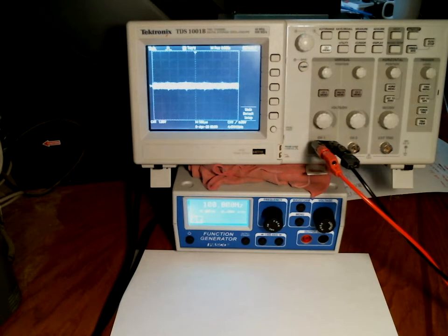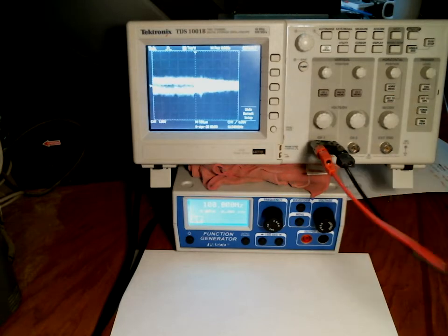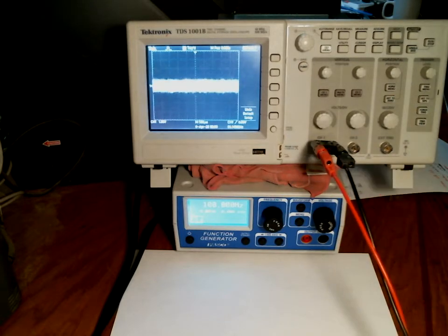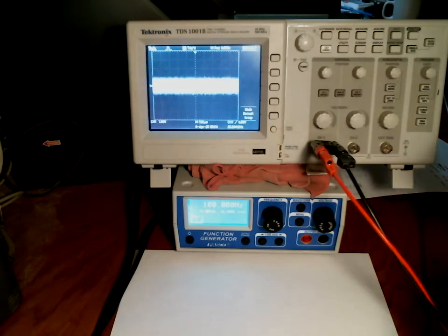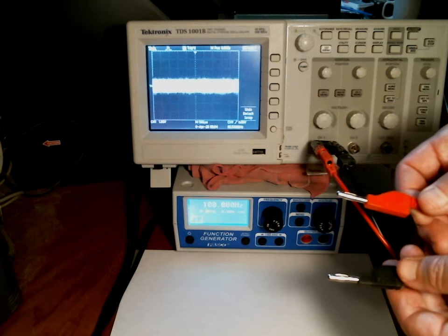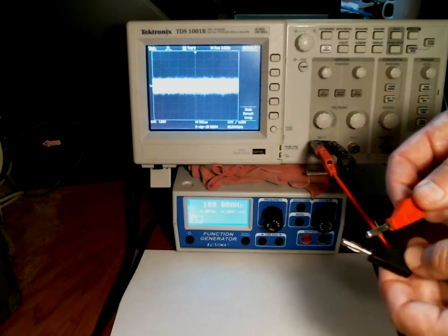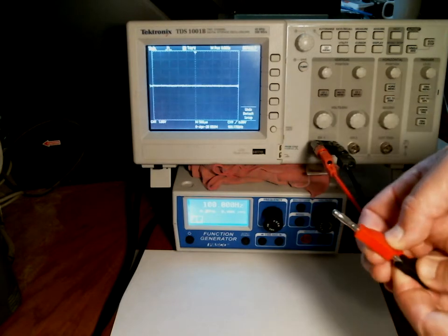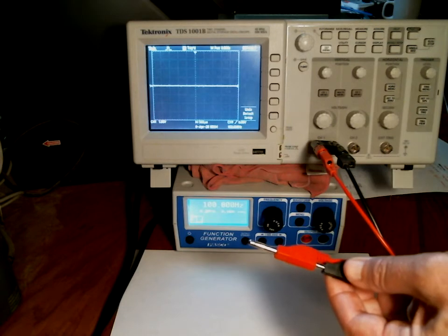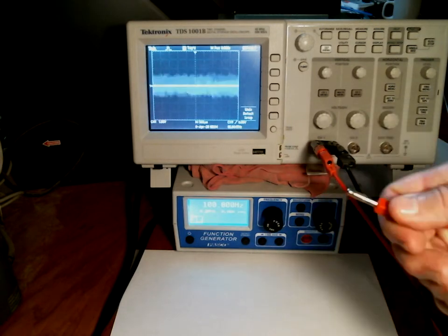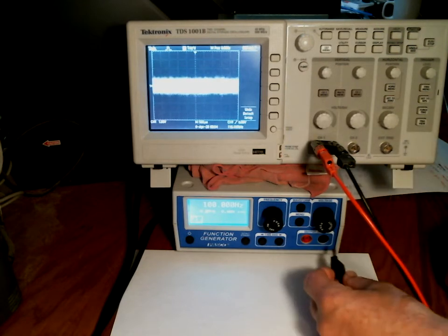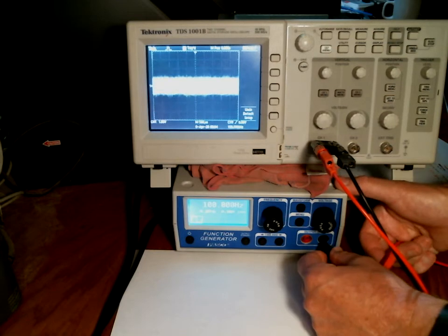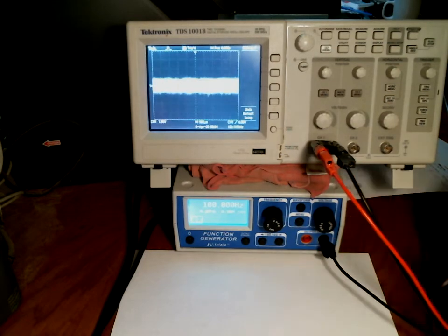So I'm now going to use the scope to see the signal from the function generator. Right now the leads are floating, so I just get some noise and nothing meaningful. If I go like that, I now read a 0 voltage difference between the 2 wires. I'm going to go ahead and plug the black cable into the black output on the function generator. That's important